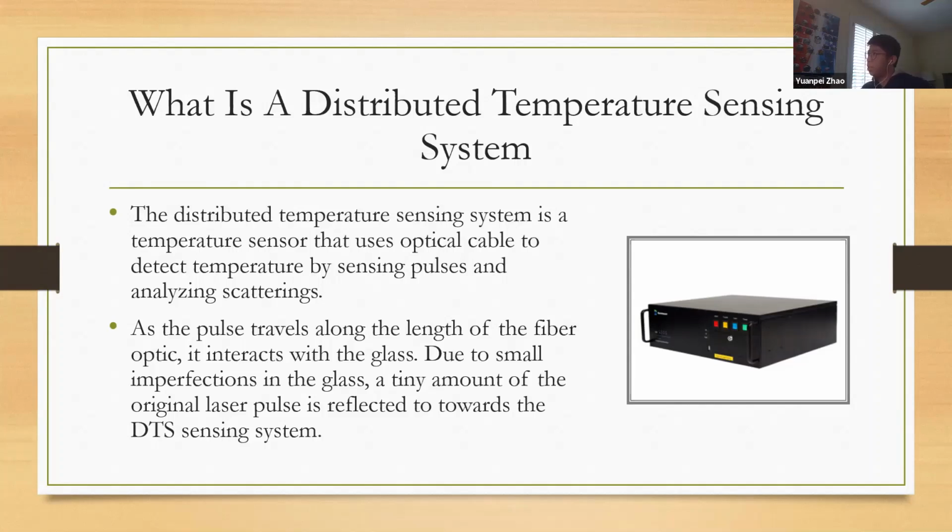Yes, the sensor can work by itself, but if we are doing experiments, we can use the laptop to show the data. Since it's distributed, each zone is about 1 meter, so we can see what happens at each meter. When there's some very abnormal temperature, like it suddenly rises very high, it triggers the alarm.